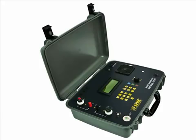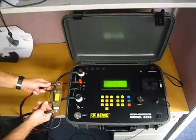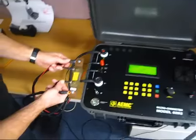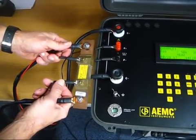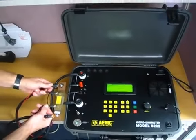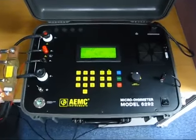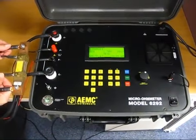Here's the 6292, and we will be using a 166 micro ohm shunt for the test, shown here. For our demonstration, we have connected a 166 micro ohm shunt to the instrument. For this test, we will run a 20-second test in normal mode with a current of 50 amps. During this test, we will take partial measurements at 5-second intervals and store the results in the instrument's internal memory.